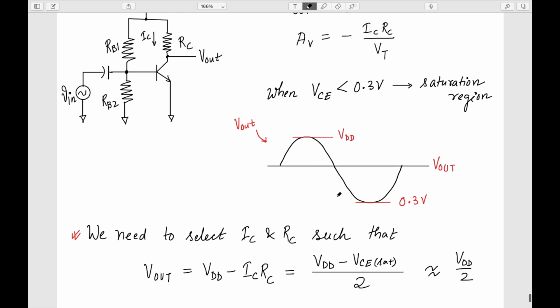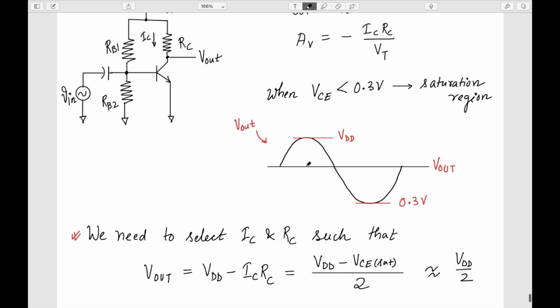Okay, so now this is the maximum swing. Of course, if you see the amplitude wise, it's going VDD by 2 here and VDD by 2 here approximately. But in the real scenario, generally we never go to this point. This is the maximum limit, so it may be lesser than that. So for the safe side, for keeping the margin in the actual design, we'll make sure that the swing is reasonably lower than VDD in the upper end, and also in the lower side it is higher than the 0.3, to make sure that the operation of the transistor is working properly.